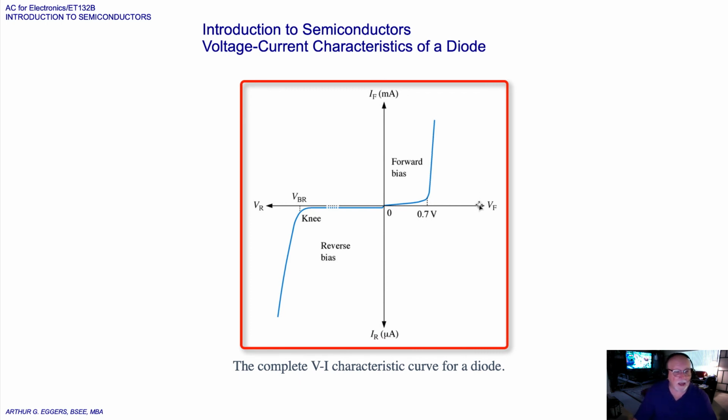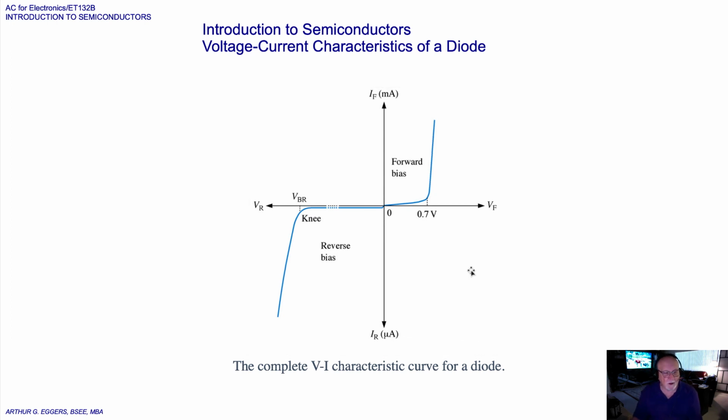So now we need to take a look at something called temperature effects. With most electronics, heat becomes a factor. So what happens when we take a look at temperature effects? For a forward bias diode, as the temperature is increased, the forward current increases for a given value of forward voltage. Also, for a given value of forward current, the forward voltage decreases.